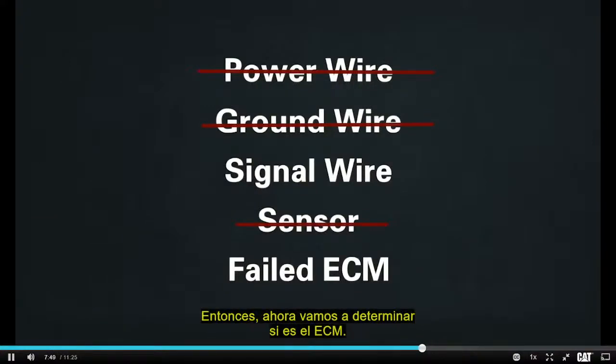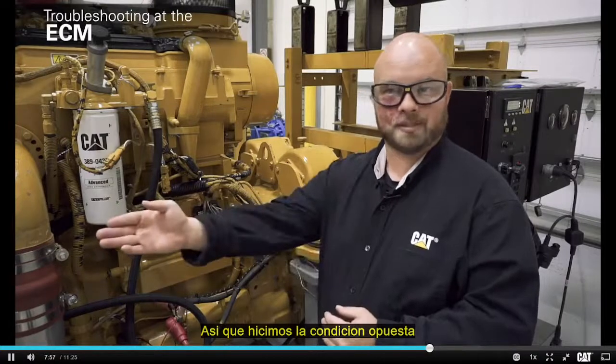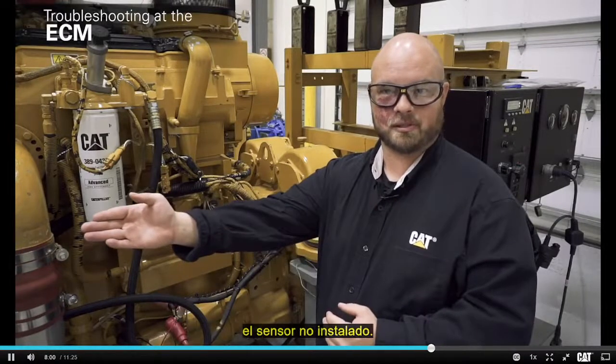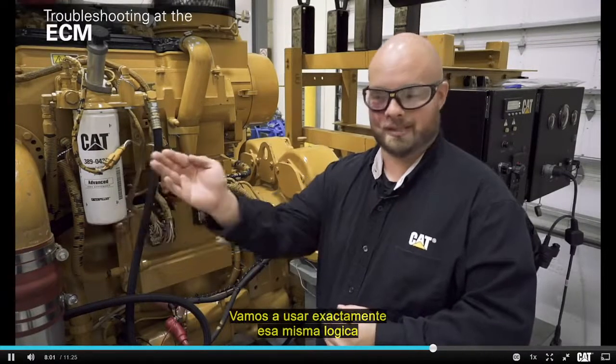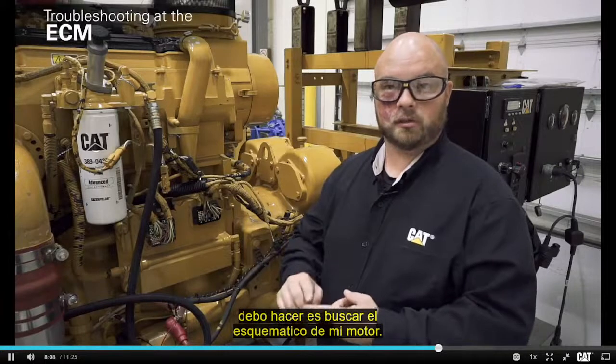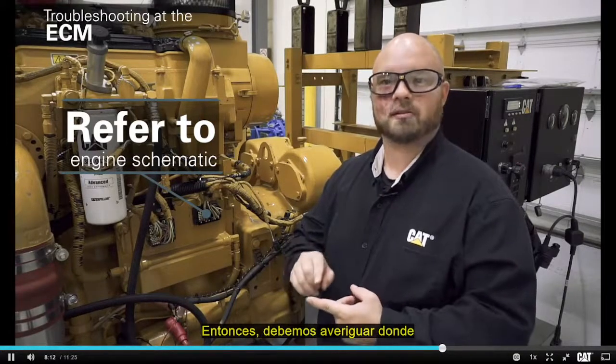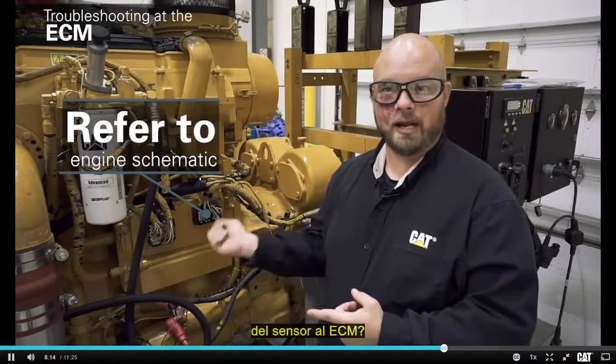So we're going to go down to the ECM. In this case, it's easiest for us to go ahead and troubleshoot the ECM. We made the opposite condition out at the harness with the sensor not installed. We're going to use that exact same logic, only now we're going to do that at the ECM. So first thing I need to do is look up the schematic for my engine here, okay? We need to find out, where does our signal wire from the sensor enter into the ECM? Which connector, which wire do we go at?